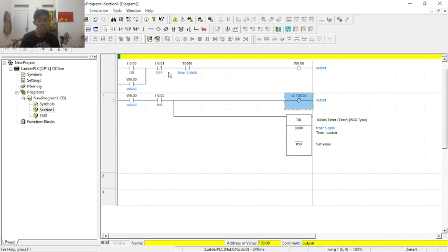So when the on contact is activated, it allows current flow in the logic. The off contact works in the opposite way. It prevents current flow unless the condition is false. So it's like a logic gate. And then there is the timer instruction T000. In the middle of the rung, there is a box labeled T0000 with the description timer pneumatic, a 5-second timer. This is a timer instruction, or TIM, in CX Programmer. It is configured as TIM000.